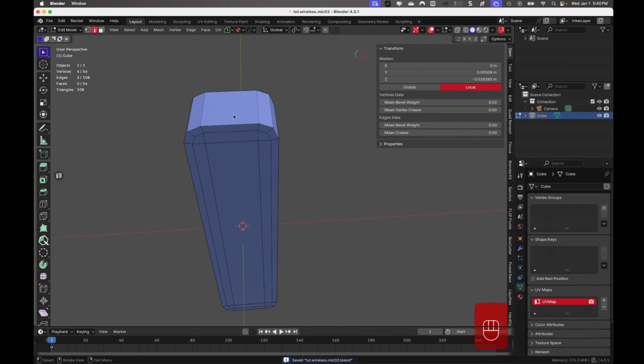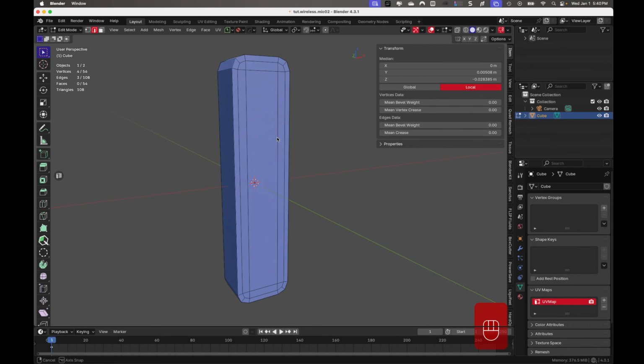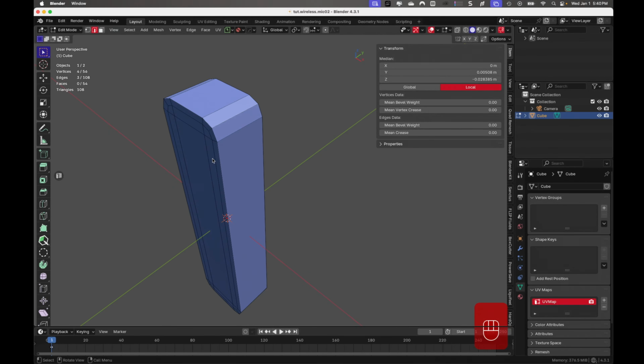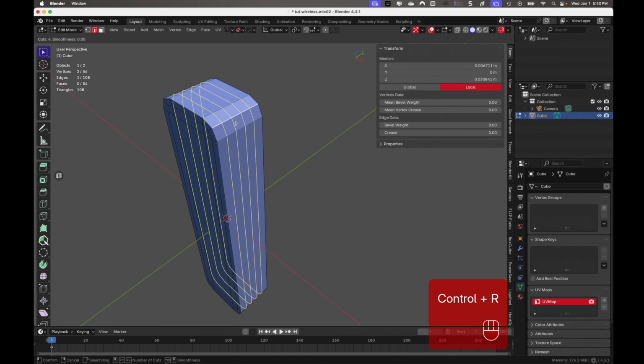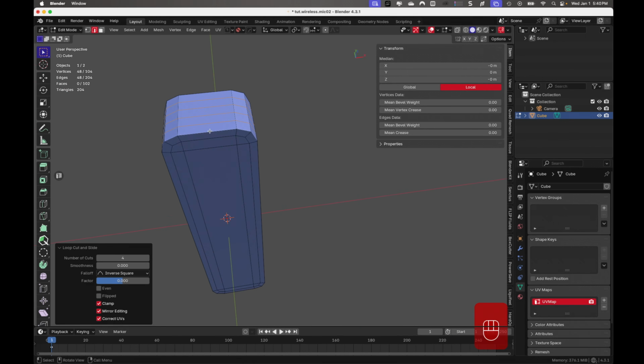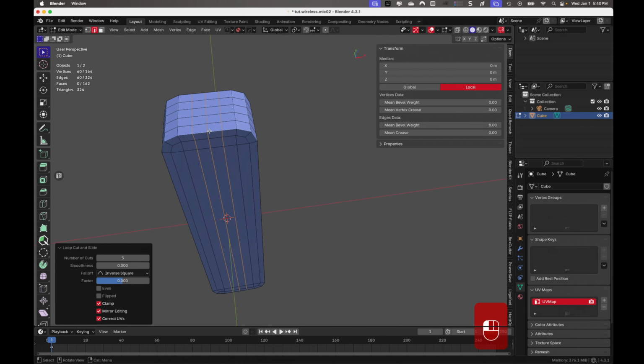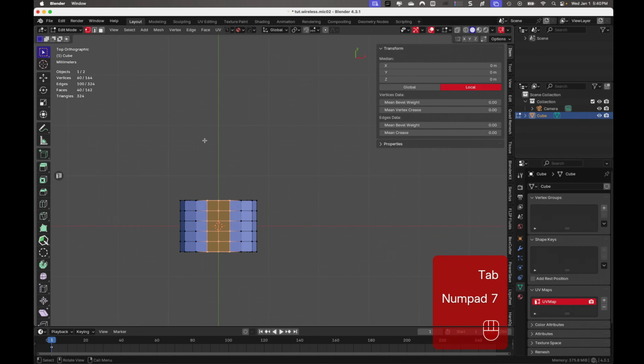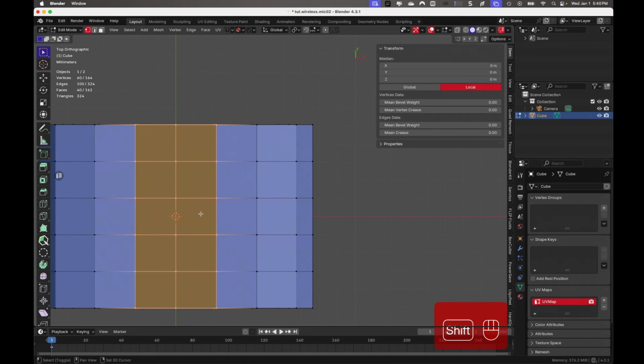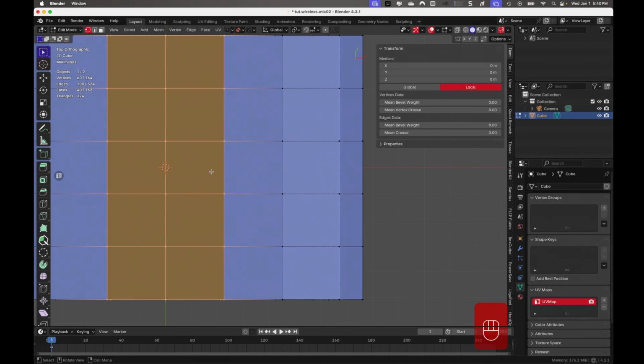I want to mimic this out where there's a protrusion that comes from the top. It's cylindrical in shape, and this is where the actual microphone is separate from the body, or the part of the microphone that listens to the sound, away from the electronics. And we need to figure out how we want to come in here and make this part. So let's go ahead and do that by adding in some loop cuts here. 2, 3, let's do about 4. And here in the front, I don't want too many because I don't want too much geometry here. And let's do 3. And then go to vertex selection mode, go to the top. And this should give us a spot here where we can come in here and make this protrusion.